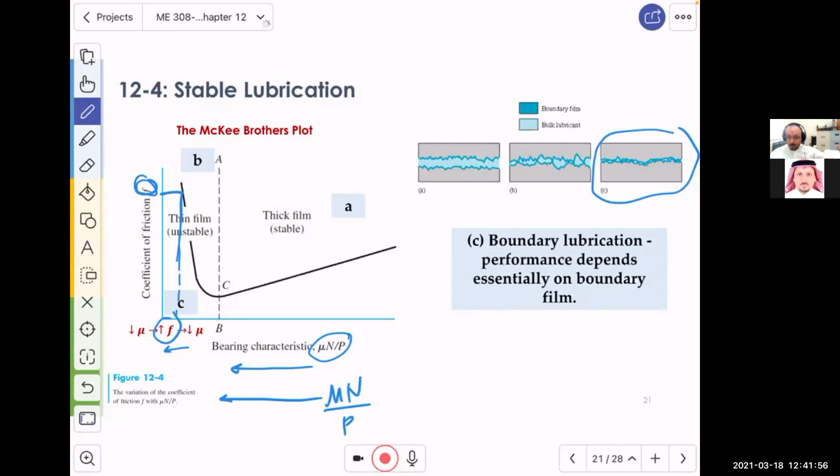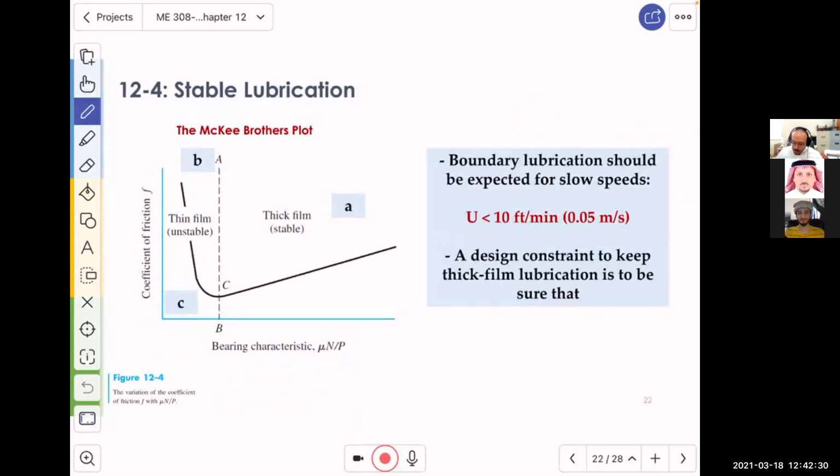You know, the difference between water and oil is viscosity in terms of this lubrication. And we need viscosity. If you lose the viscosity, the fluid will not give you the lubrication that you need. And that's why it's unstable. You drop the viscosity, then the friction increases, then the heat increases, then the viscosity drops even more. And that's why we call it unstable. You got me, Shabab?